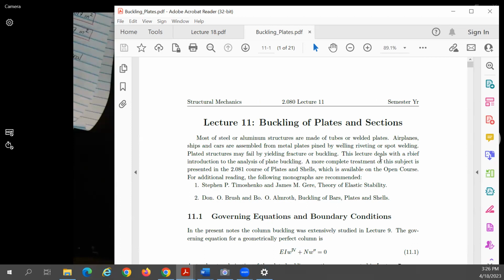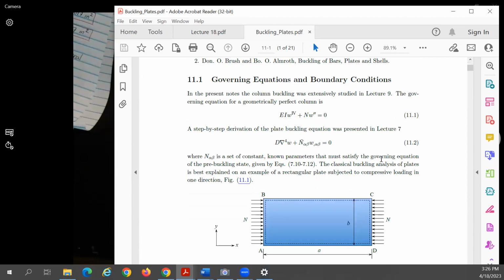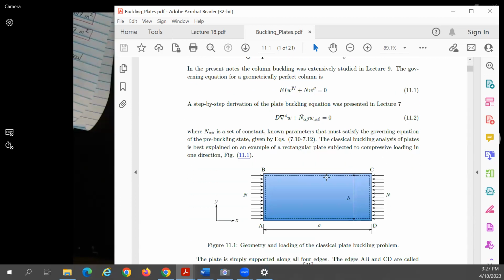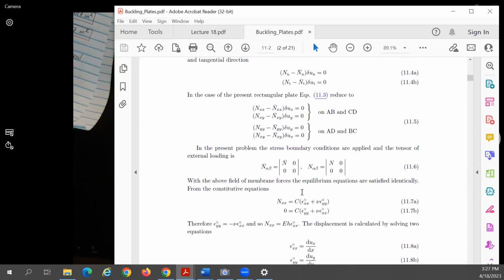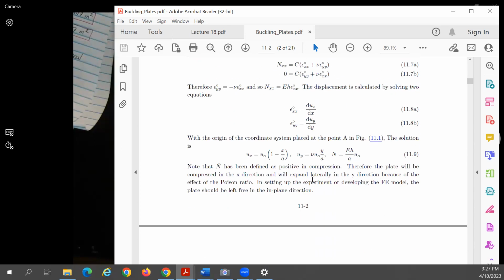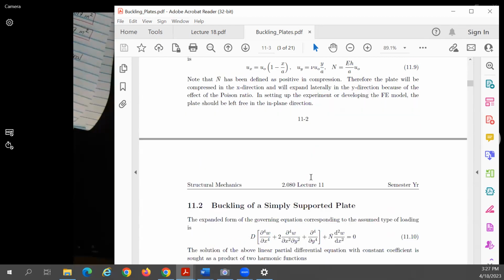So basically, I will add this document online. What is buckling? This is like what I was doing with the pad. This might be a panel. Now you apply an axial force. Okay. So this panel is either going to be stable or unstable, no? Until it buckles. So it's a complicated problem because you have a nonlinear in-plane force. Okay, so this is two-dimensional. This is from a class called Theory of Plates and Shells. It's a graduate class over here, at least.